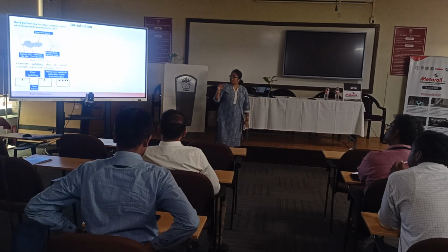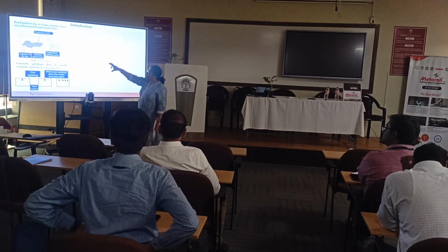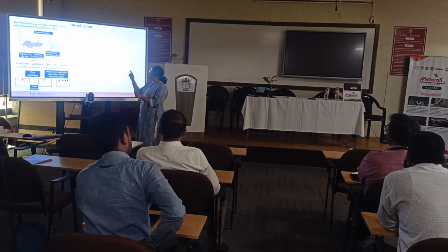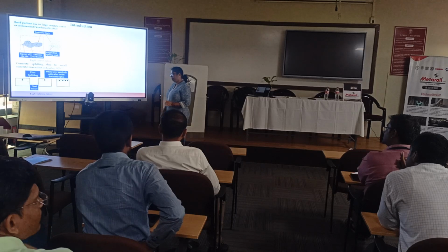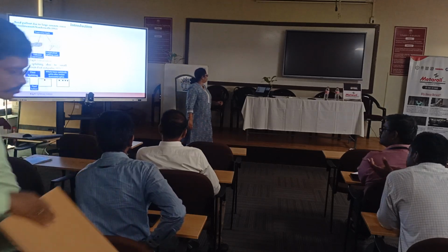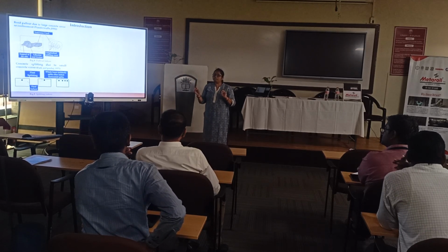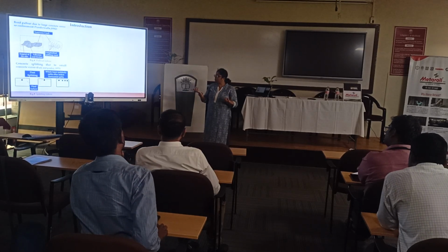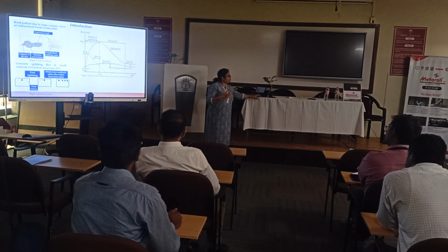So what is the strength that I told you? The steel has ribs as well as some adhesion and friction, which allow the concrete to grip. But if you have more load with a large grade of steel, then the cracks rapidly grow in a radial manner, which is called a splitting crack. Now the splitting crack is very dangerous, because with a small force it allows the concrete cover to go. When the concrete cover is gone, what happens? Steel is exposed to the environment. Then what happens? Rust, corrosion, and structural capacity is lost. I am not explaining this in detail; I think I am running late.